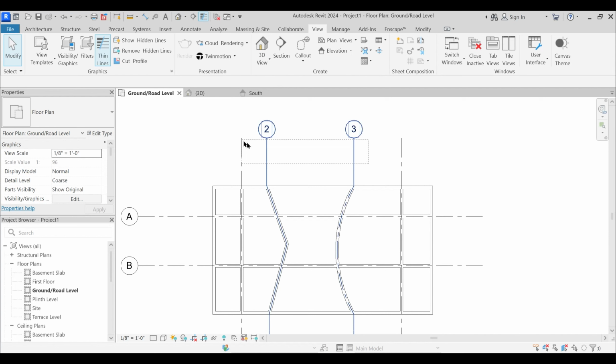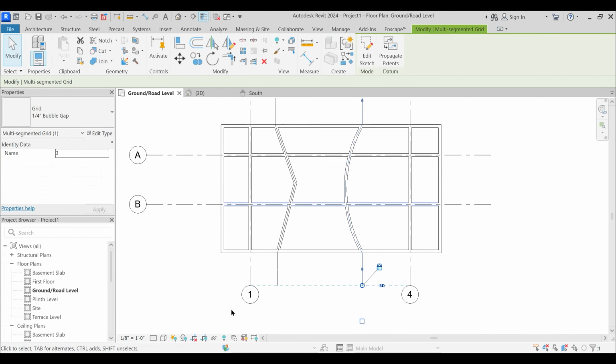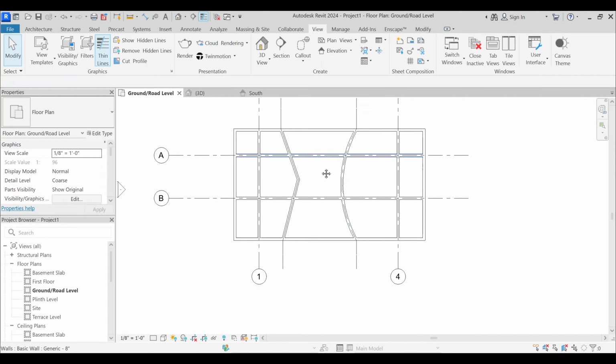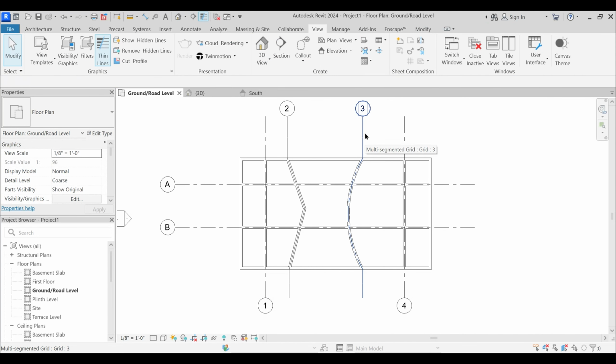for today. There are going to be a lot of commands, but another command for today is that if I select any of these lines, then you see that here there is the eyeglasses icon. Fine. If I click this, then you see that there are four different options. There is isolate category or hide category, isolate element or hide element. If you want to hide or isolate the elements that belong to a category, you need to select isolate category or hide category. But if you want to hide or isolate a single element, then you need to select likewise.